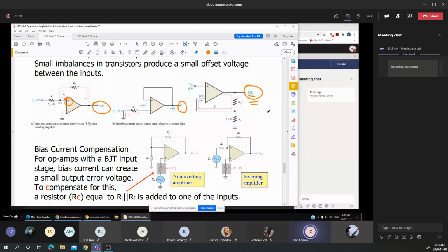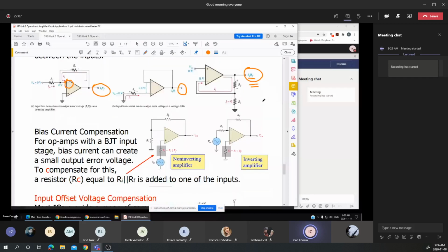We discussed the input circuit of the op amp. Okay, we discussed the differential amplifier. Always there is a small difference between the two transistors, or between a set of input transistors. Even if we are trying to make the same transistors, the same resistors, a small difference will cause the output voltage not to be 0. Again, ideal should be 0, practical is not 0.